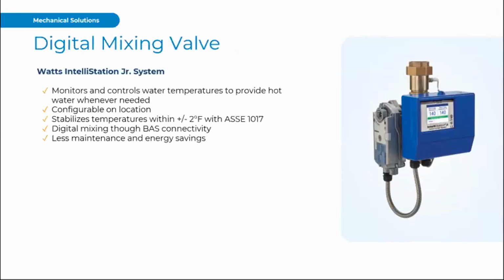Highlighting some of the other options on the market, Watts has their version of these digital mixing valves, the IntelliStation, which, just like the Lawler version, has a more stable output temperature. Watts is offering only plus or minus 2 degrees and has many configurations to match site conditions, flow rates, and other requirements that you need.